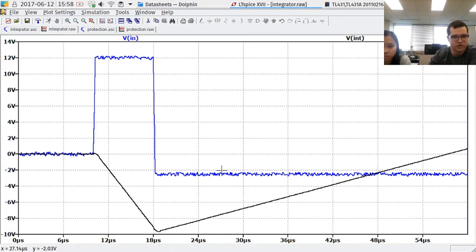So if we take a look here, here's our input voltage. Worst case input voltage is 12 volts. The timer will run for 8 microseconds, which we found is a nice balance between speed and linearity, because since there's a fall time here, this curve shows up. We also simulated it, like I said, with noise.